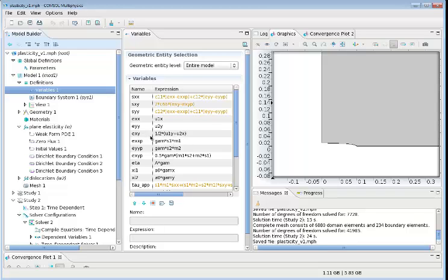we have to do, we have these zeroed out. So you need to go in and, using the definition I gave you, this is my plastic strain. So this is gamma times the slip direction and plane. Here's the other normal strain. And our shear strain is made symmetric like this. Alright? Everything else is the same here.